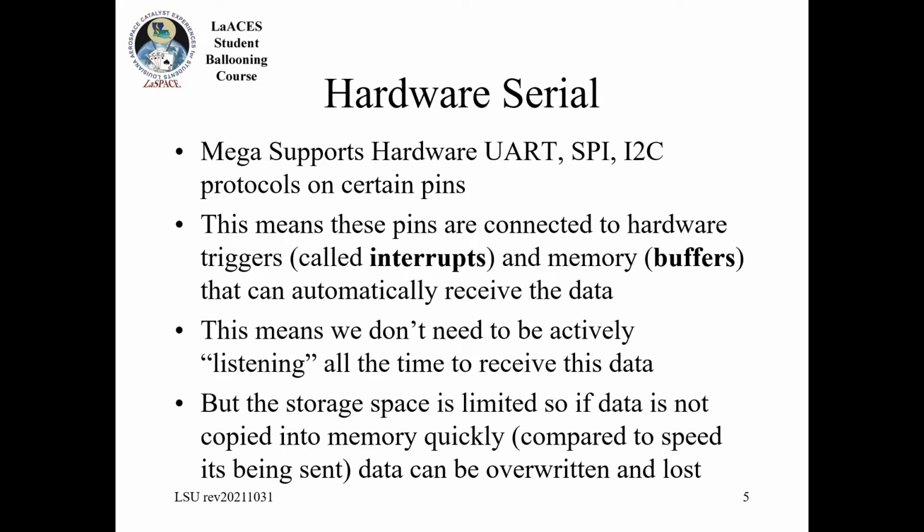Whereas if I was in a software mode, I would basically have to go look and be waiting to catch the data when it got transmitted. And if I wasn't actively listening to those pins when the data was sent, I would lose it.